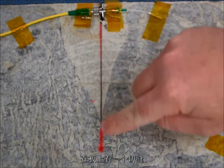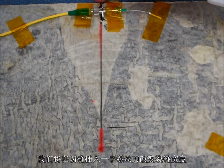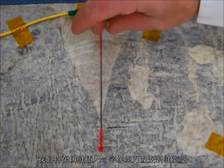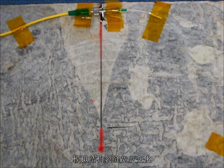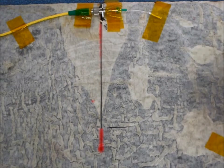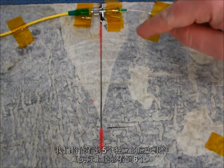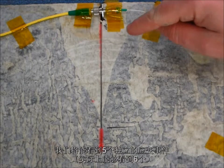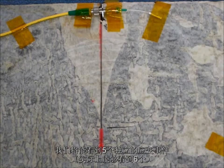We have made a cut into this sheet to which we are going to insert a wedge to expand and contract the cut, simulating the formation of a crack within a structure. We will demonstrate how you can detect the expansion of this gap, as 5 separate events along the fiber.